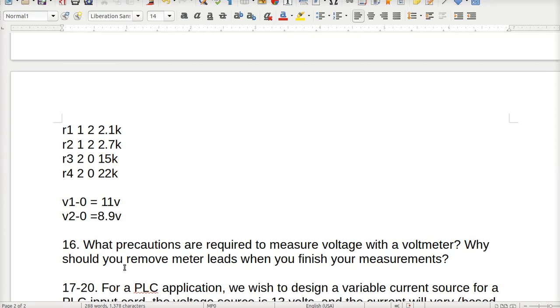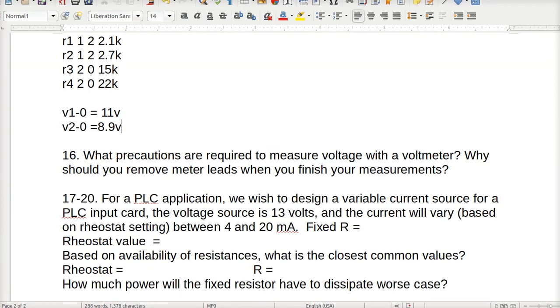So those are your fault conditions. I made the measurements for you. Now what you've got to tell me for this problem is, what did I bug? And a bug can either be an open or a short. So don't just give me a resistor. Give me whether it's open or it's shorted. Okay? You know how to do that. You can do it both ways now. And that will be great.